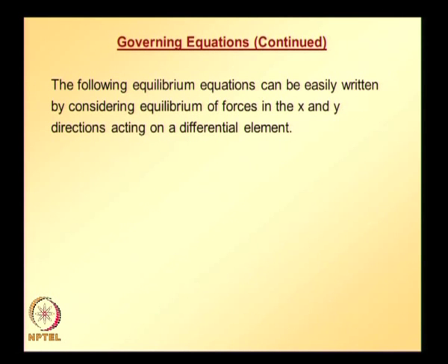The following equilibrium equations can be easily written by considering equilibrium of forces in the x and y directions acting on the differential element. So, the first equilibrium condition results in this equation, second equilibrium condition results in this equation. So, basically the entire governing equations for 2D elasticity problem start from here.